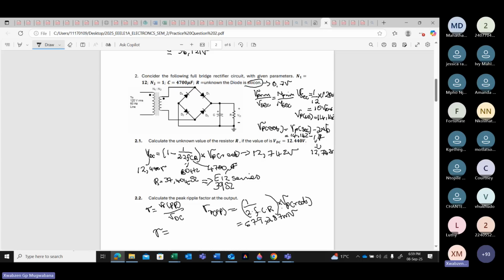You will see that on that example, they showed you that when you do the bridge rectifier, your filter needs to be doubled. Are we together? Your filter needs to be doubled because remember, you're taking two signals, the positive signal and the negative signal, and then you're pulsating both of them on the first quadrant.